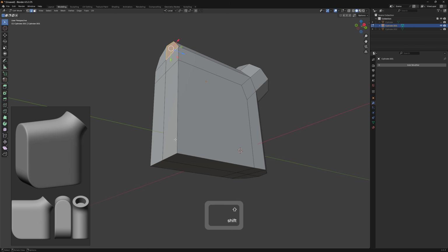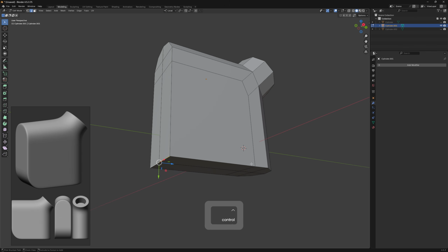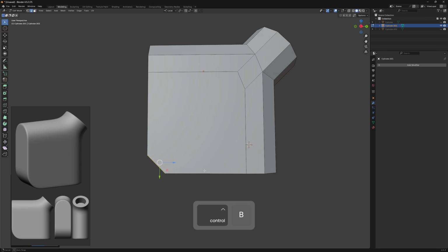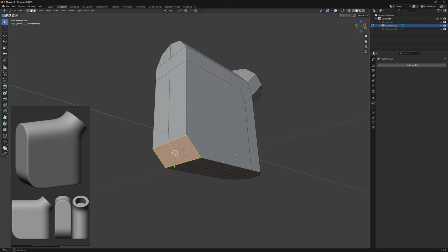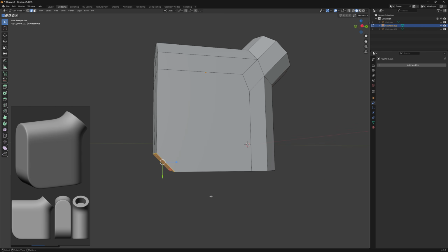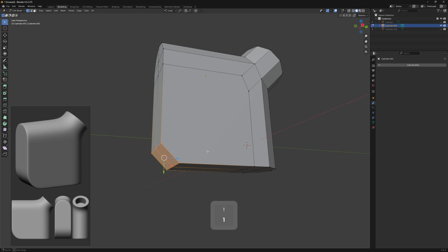Okay, now it is time to work on the last detail, which is that round part at that corner. So I will select those edges, Control B, bevel these out with 0 subdivision. This is the important part of the process of creating that really nice and precise rounding. Then I'm going to select the cut tool. I will start from that point and go all the way around.